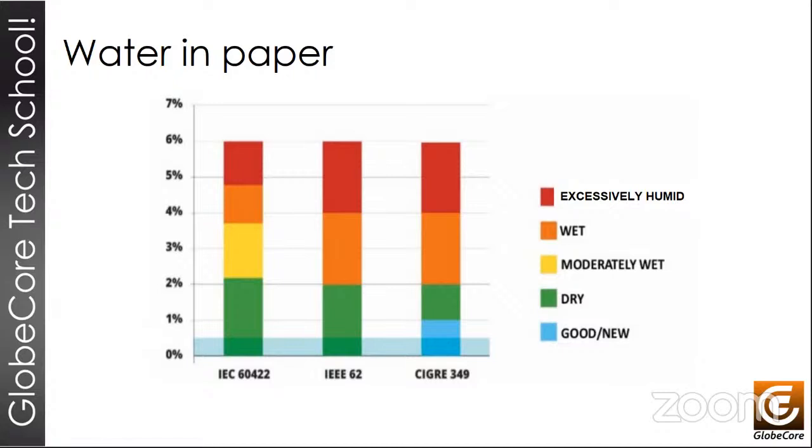And high moisture levels in transformers are obviously undesirable, since paper is constantly being destroyed by this moisture, and there is a danger that the transformer may stop working in a critical failure. Such failures may even cause the transformers to go out of service entirely. It may require some major repairs, and in some cases the transformer cannot be repaired and will have to be written off entirely. Next slide, please.